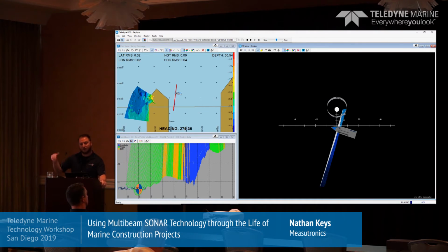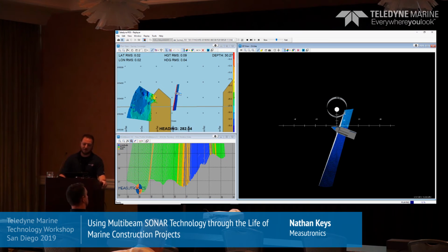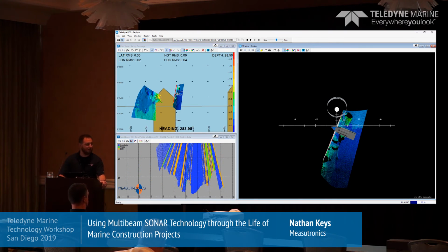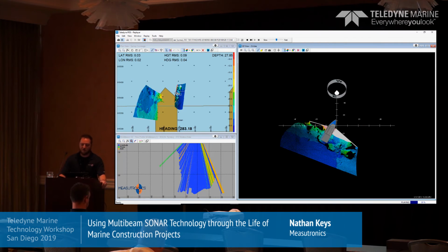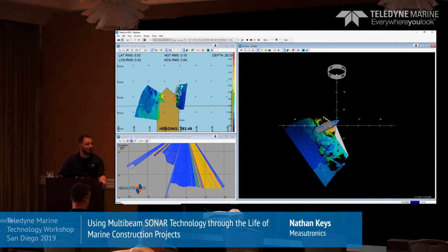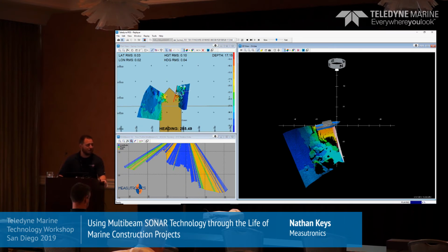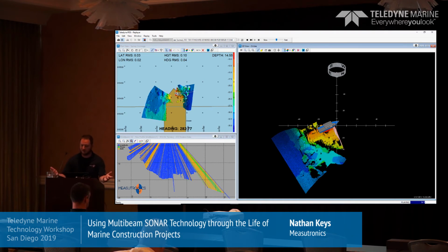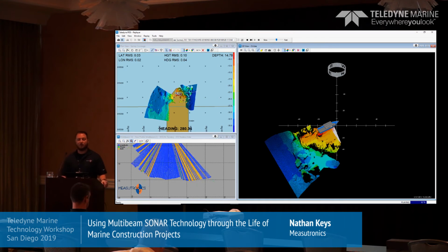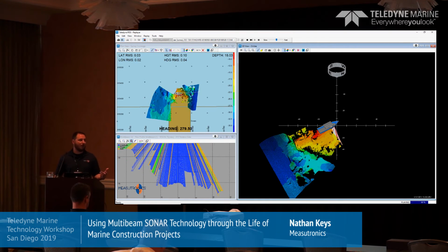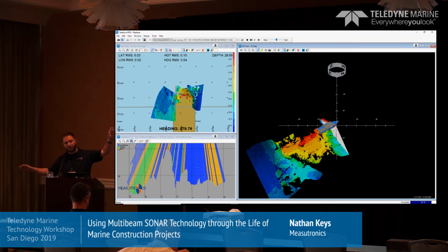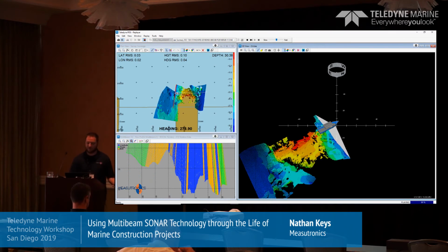They were using hydraulic jackhammers to beat the bridge down, including the underwater surfaces. So they had a T20 on a boat, and the boat would go by and do a scan just like you're seeing now. They had a certain level they had to beat everything down to, and the scan would show whether they had met that level or not. If they had met the level, then a clamshell crane would come in, pick up all the rubble, and they'd finish it that way.